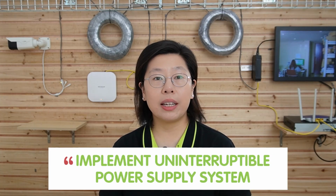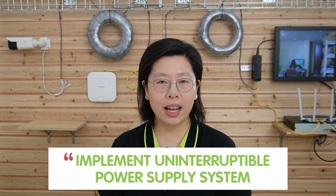Additionally, implement an uninterruptible power supply system to provide backup power during brief outages or fluctuations, ensuring continuous operation of your PoE devices and maintaining the reliability of your camera system.